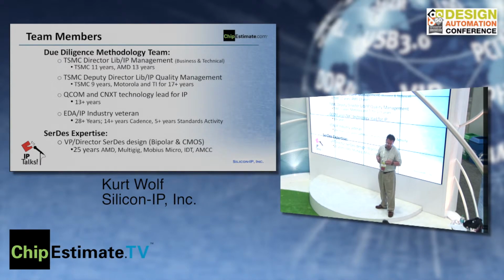Our team members come primarily from the foundry background. Myself and another colleague at TSMC built what's called the TSMC 9000 program, which is the multi-stage approach to validating pre-tape out IP, silicon IP, split lot IP, to make sure that the IP actually performs to the datasheet specs across process, temperature and voltage conditions.